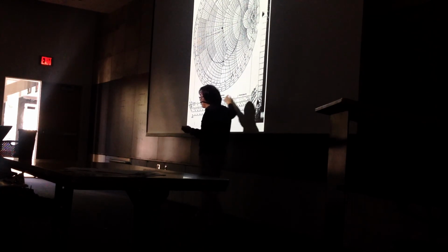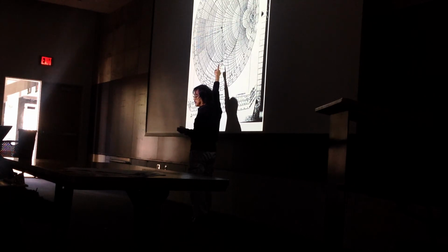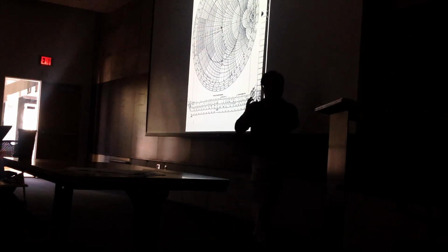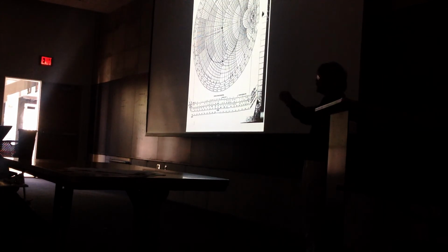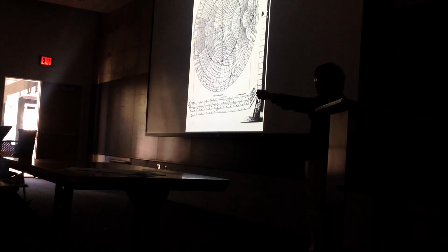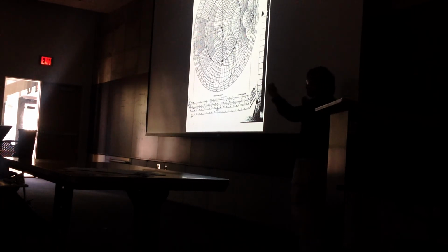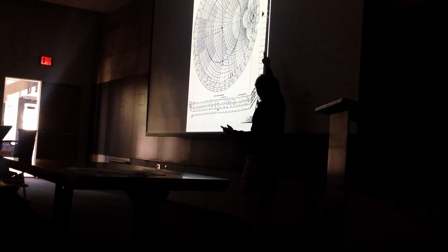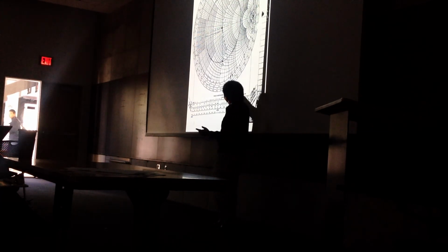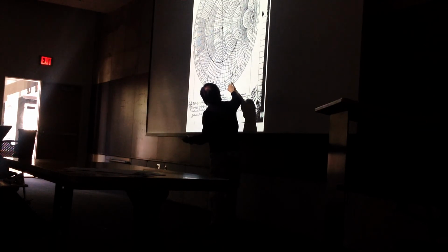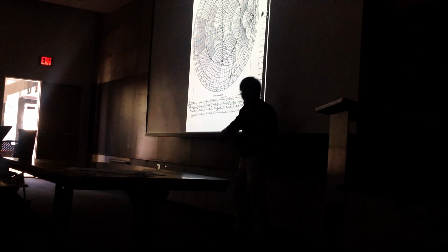If you make it long enough, it will become a capacitor. So a short circuit can behave like an inductor, or like a capacitor, depending on the length of your transmission line. Now, in order to get that admittance to be minus 1.5, you go from that point and rotate to here. You read from your Smith chart here, this is about 0.3 something, and that's 0.25.